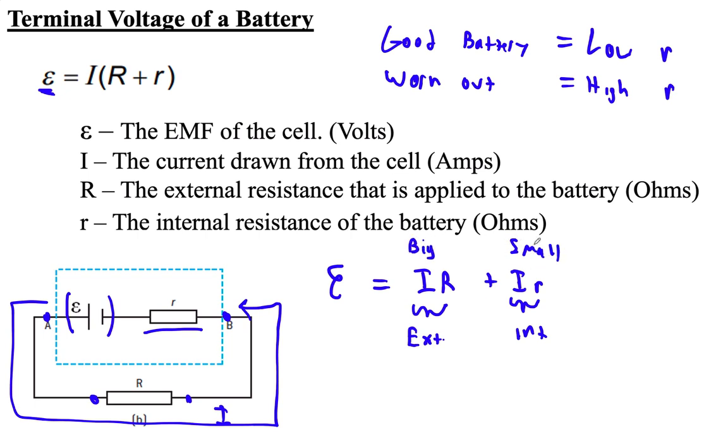But because of this small voltage here, the actual terminal voltage of the battery, if we solve this for IR, the external circuit voltage, is the EMF minus the current times the internal resistance. They don't have this formula, but it's a very useful concept. That should make sense: the voltage will be the EMF minus this Ir. We could do it with Kirchhoff's laws: if the current's flowing this way and we go this way through the circuit, it's going to be minus Ir plus EMF, which would be this.